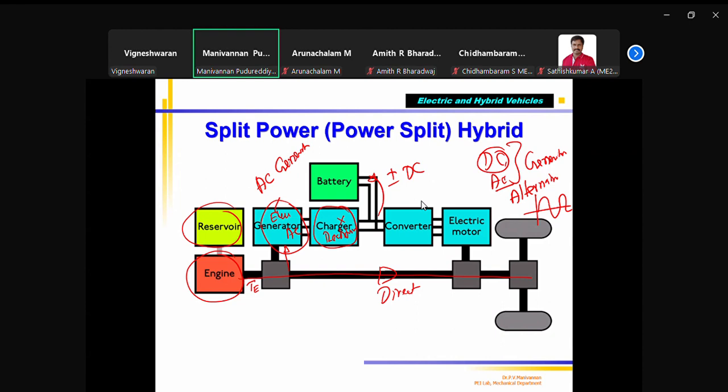So many hours, this is the current you need to supply. 2 amps per hour, correct? 2 amps for 10 hours, or 5 amps, for example, 4 hours. You have to see the battery manufacturer. They say what the charging rate and discharging rate are. Specifically, charging rate is very, very important. Sudden discharging also is not possible. Battery won't supply. Okay. Charging, you should not overcharge; too much charging you also cannot do.